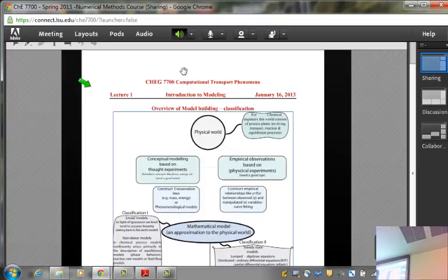Traditionally we have been designing intuitively. Okay. What does that mean? Let's take a distillation column as an example. If I have a feed of mixtures and I want to separate them, and the mixtures have different boiling points, I can exploit that difference and set up a temperature gradient in a column, and then I can draw the products, because each particular level or stage will have a certain temperature and only certain compositions can live in the liquid phase, for example. So I can separate the light ends to the top and the heavy ends to the bottom.